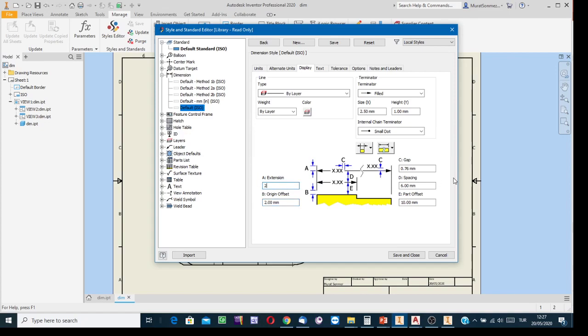2 I selected. For the first dimensioning row, the space to leave between the outmost boundary and the dimensioning line is 10. For the successive ones, it is 8, minimum 8.